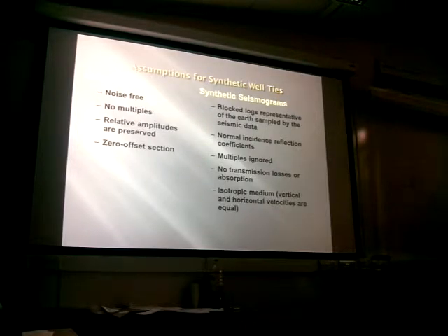You assume that you don't have any transmission losses or absorption. Now, a lot of the synthetic software allows you to take into account the spherical spreading, so make sure that you are taking the spherical spreading. Spherical spreading, remember, is the way the density of the energy of the P wave that is moving far from the source is redistributed across the front of the wave.